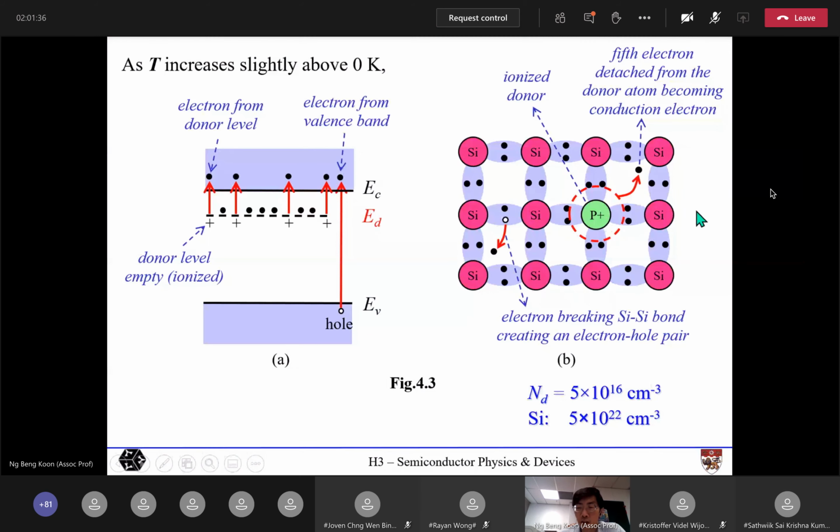It cannot physically move. So this positive charge will not conduct current. You need to be able to distinguish this from a hole. A hole can move. This ionized dopant doesn't move. It sticks in a position in the crystal lattice.